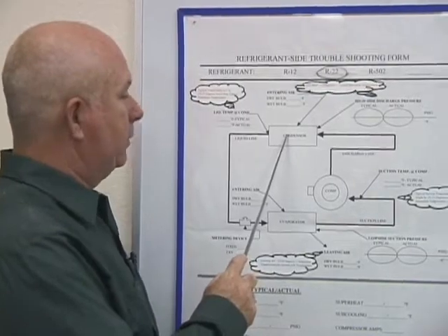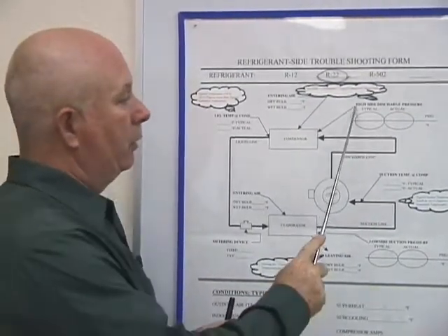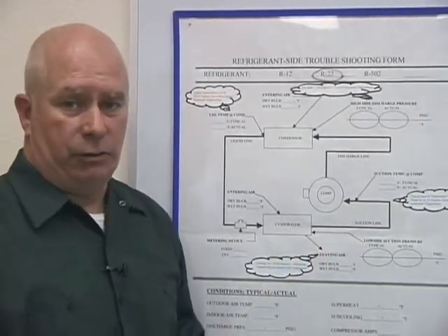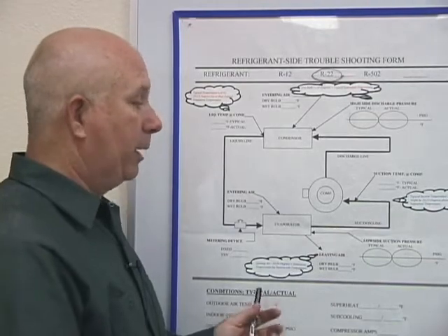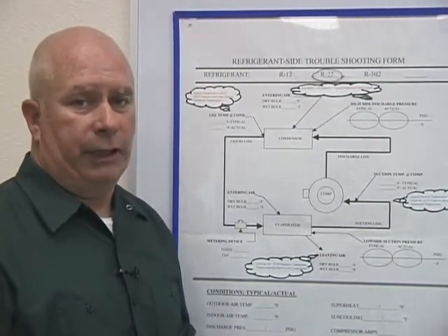So that's the condenser. Now, you're going to also take what is known as your high side discharge pressures from your gauges, your manifold gauges. And depending on what type of unit it is, it'll determine where you're going to take that.